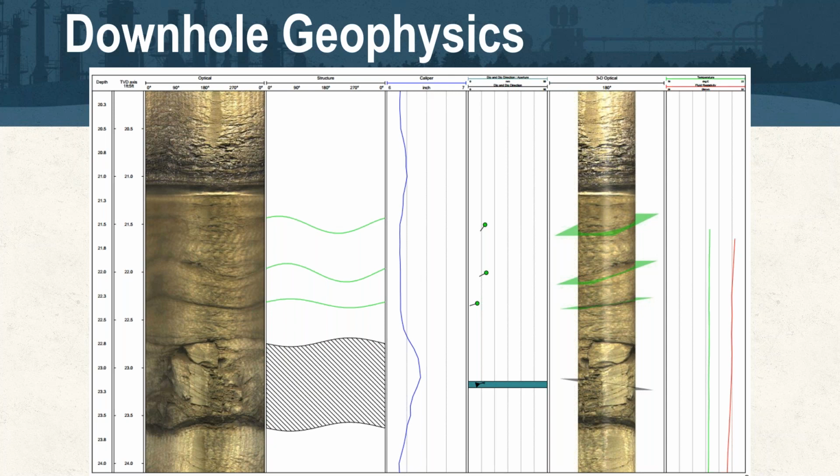Yeah, if there's concerns about borehole integrity and significant potential expensive loss of hardware, we do have a drilling method that we just call pre-drilling. There's other presentations that can highlight this more in detail, or we could share it with the listeners offline, but essentially it involves pre-drilling the hole to the total depth of the remediation and backfilling that borehole with a bentonite seal from bottom of the hole to specified depth below grade. And then what we can do from there is go back in and trip in with direct push tooling and complete remediation as if it was an overburden type setting.